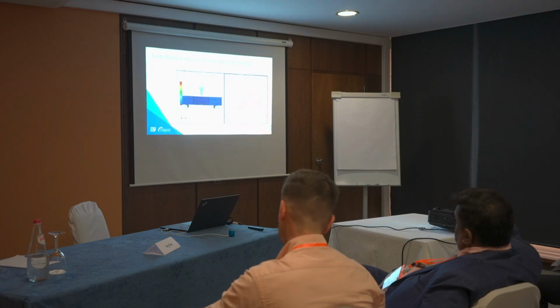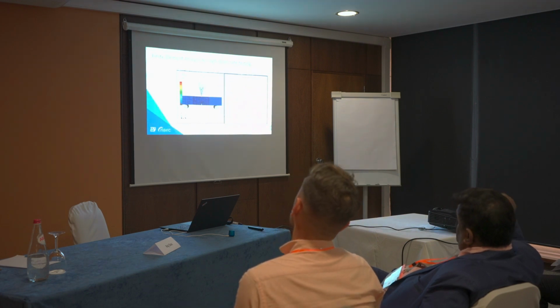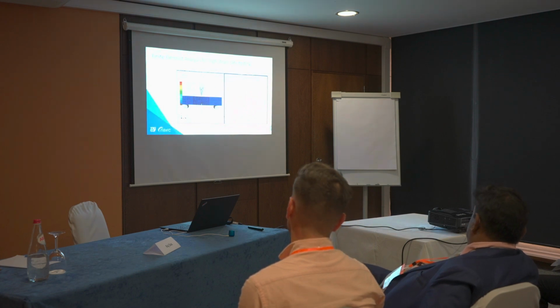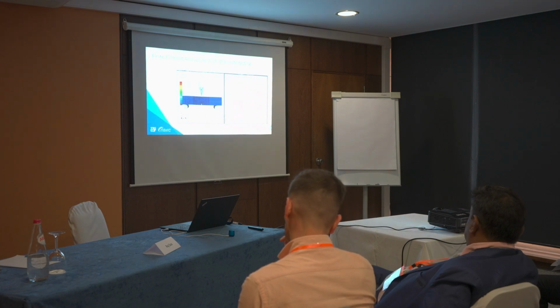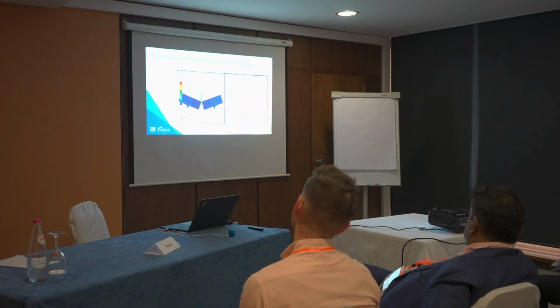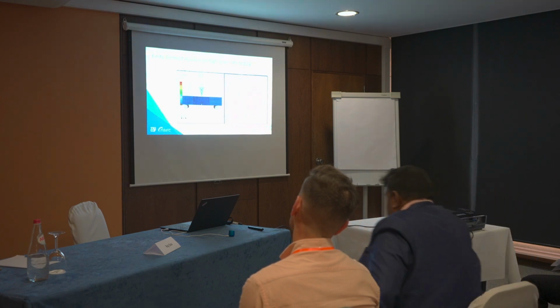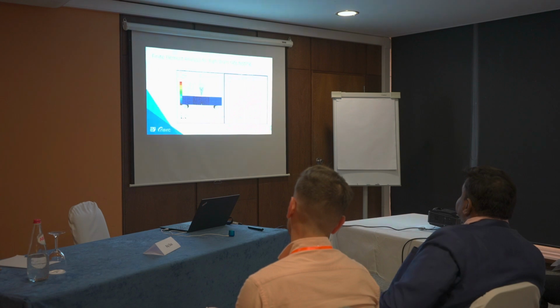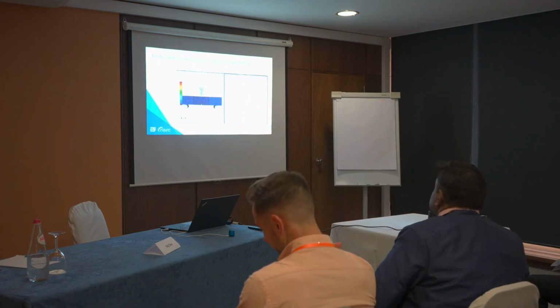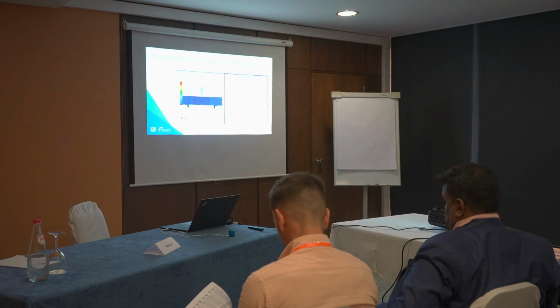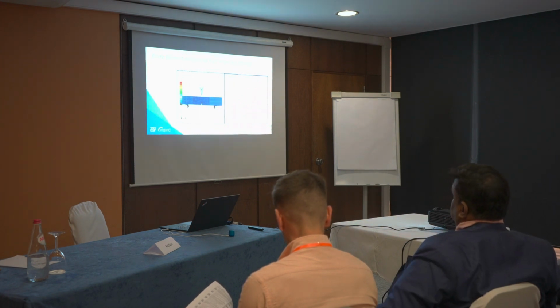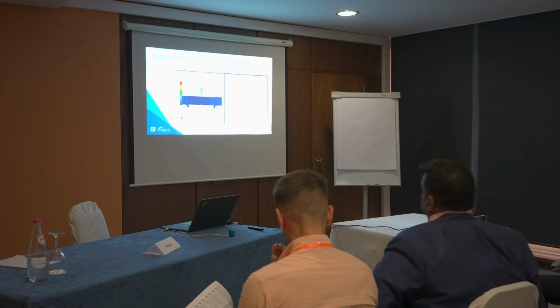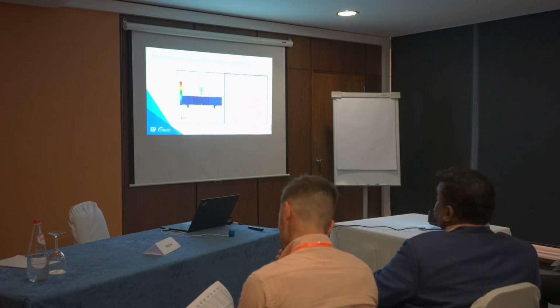We went ahead to use finite element analysis for these high strain rates, where the hammer is dropped at different velocities, and we record how this propagates. We see that the hammer is dropped from a distance, and gets into contact with the specimen. Then it continues until the fracture propagates. I forgot to mention that we utilized different notches, about a 5-millimeter notch and also a 2-millimeter notch, as we see in this simulation.